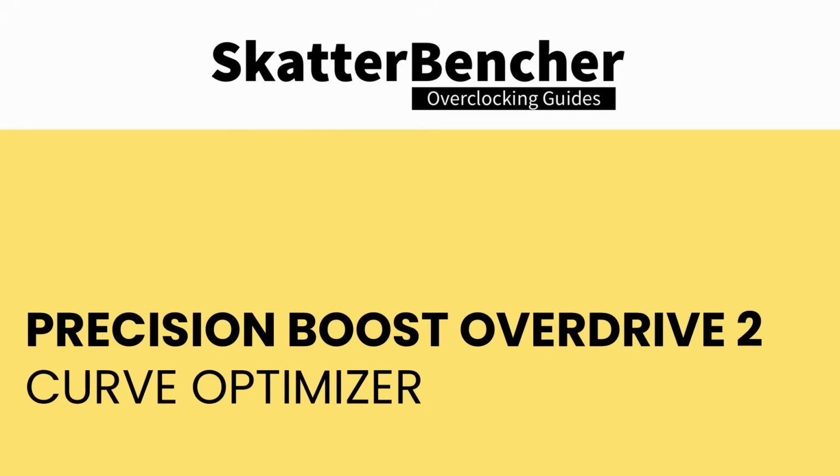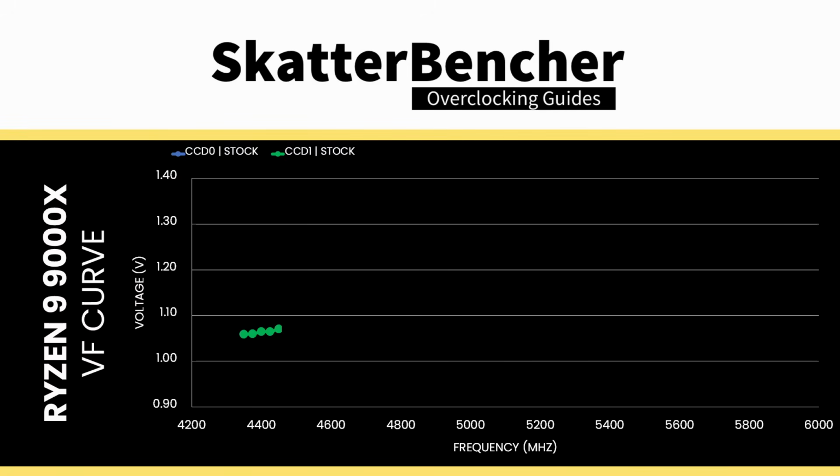Curve Optimizer has been one of the most important tools of the Precision Boost Overdrive toolkit. It's most commonly known for its undervolting capabilities, but on AMD Ryzen CPUs, it kinda also acts as an overclocking technology. To explain what I mean by that, let's start with the basics, the voltage frequency curve. Here's the default voltage frequency curve of my Ryzen 9 9900X processor. You'll find that there's in fact two distinct curves, one for each CCD.